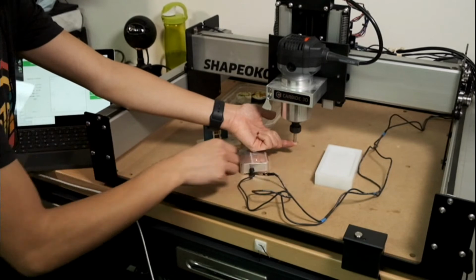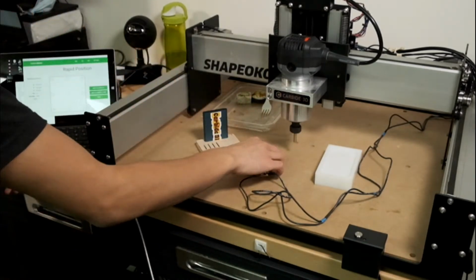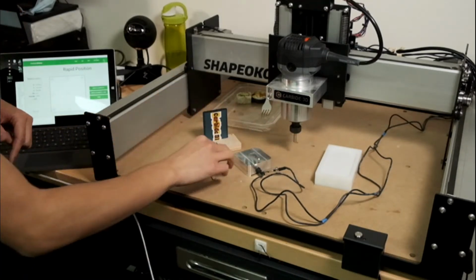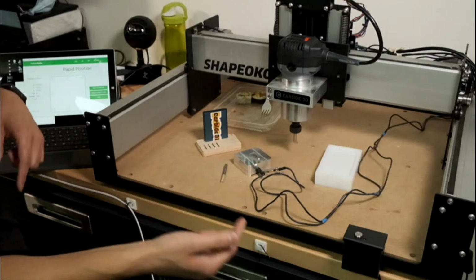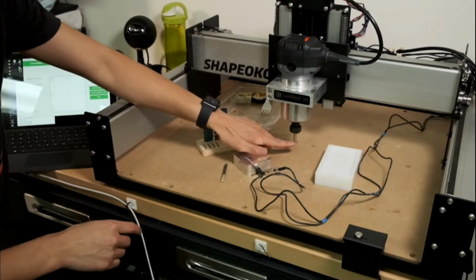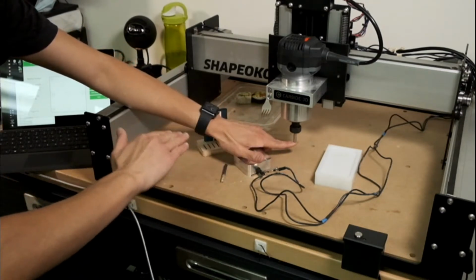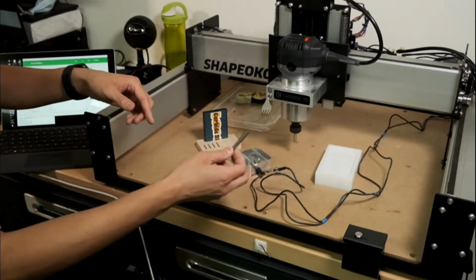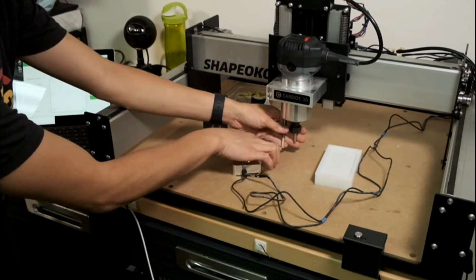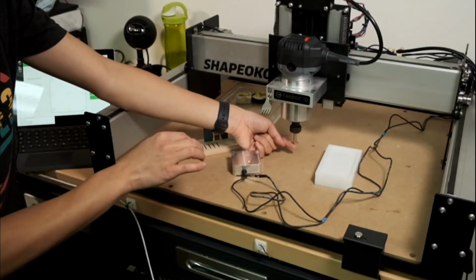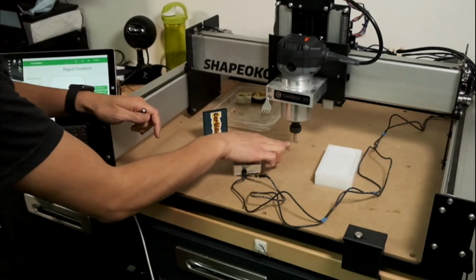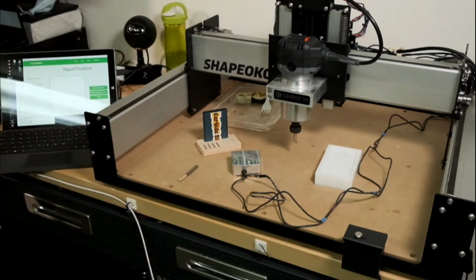despite using a longer tool. That way, when you jog, when you're trying to figure out where you should be, you can trust that the position of the end mill is going to be the same regardless of what tool is in there. And it does that check before you start jogging, because if it didn't know how long this was before you declared this position to be your reference point, when you do load in a tool and the machine does know how long it is, it doesn't know where this is relative to that imaginary point it started from. So to start off, the machine needs to know where that was, what that offset is.